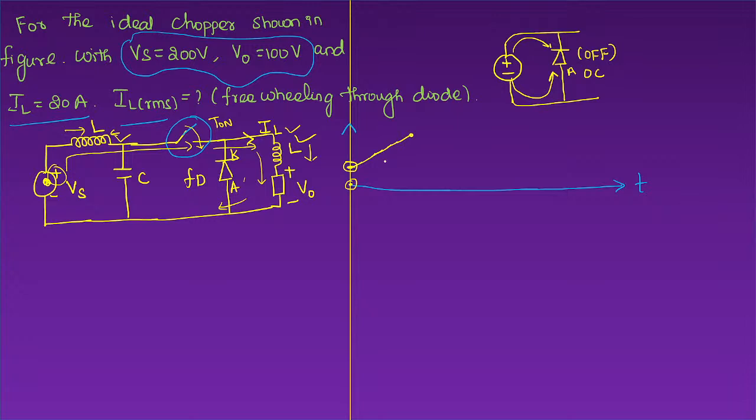Then it will go up to the maximum value. Till the moment you switch off this circuit, I maintain this on state for a particular time. Till the maximum point of your on time period, suppose it is 10 milliseconds, your inductor will be continuously charging and it tries to achieve the maximum peak current. Then the moment you switch off this circuit, what will happen? Initially the inductor was behaving as a short circuit, and it was trying to store as much energy as possible inside it.